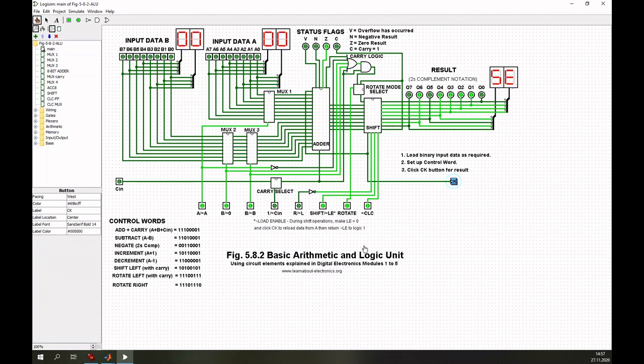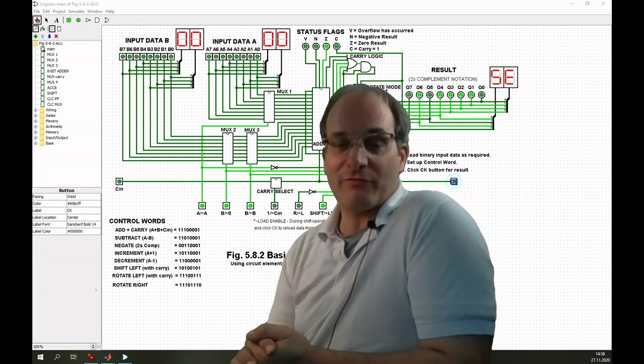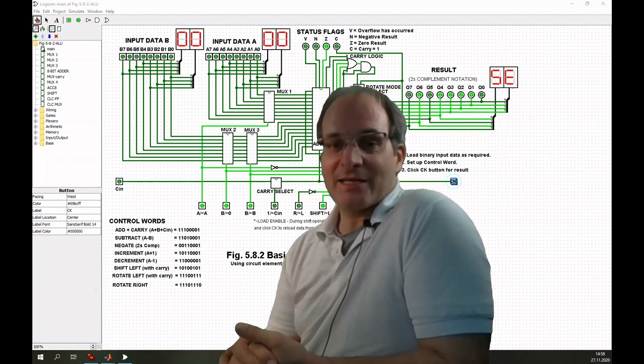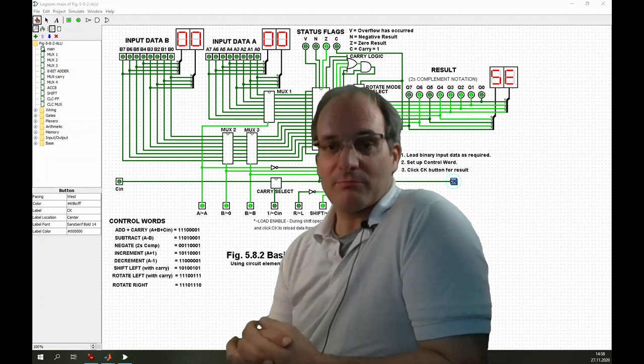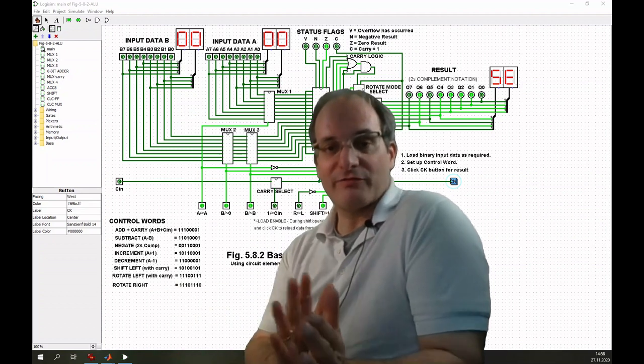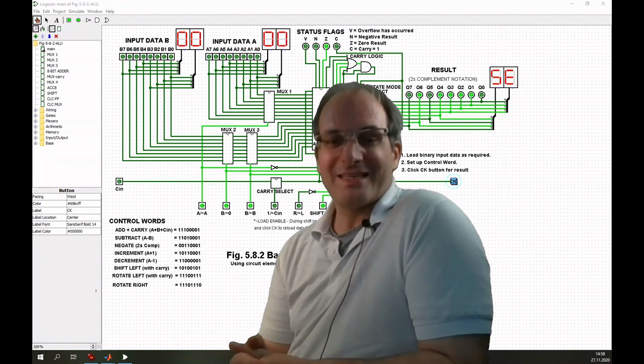And these two operations, shift left and rotate left, are quite important because you can manipulate data. For example, if you have input lines which you have to check, so that you can check if some switches are on or off, or if you have special error codes. It's often used in this case, and also for multiplication with the base 2. So multiplying with 2 is just shifting, and therefore you have simple tricks, simple methods to deal with these things.